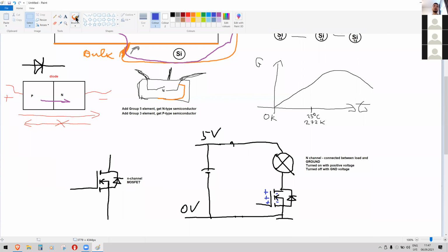So you have to connect it strongly either to 5 volts or to 0 volts to discharge this charge. Otherwise, there's still some charge. Yes, it disappears over time into air, but this transistor stays semi-open, and this light bulb kind of shines a little bit, and this transistor can actually get damaged because if it's half open, half closed, then all the power is on it. It's not 0 volts, it's not infinite resistance. It just starts to heat. So you have to connect it either to 5 volts or to 0 volts to shut it.